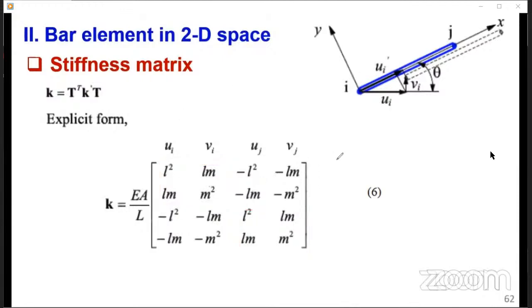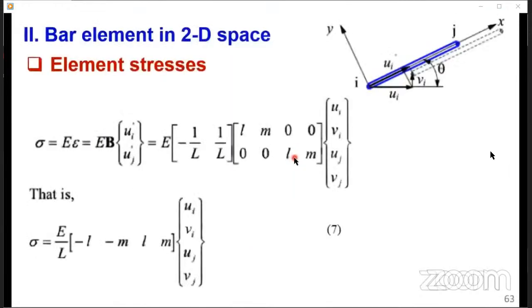And that's the equation that we use to transform from the local coordinate system to the global coordinate system. Of course, from that point, everything else goes the same procedure that we have been following. Once we assemble the stiffness matrix, you introduce the boundary conditions, you solve the equations, then obtain the unknown quantities, maybe forces, and then you can also start recovering derived quantities like the stresses.